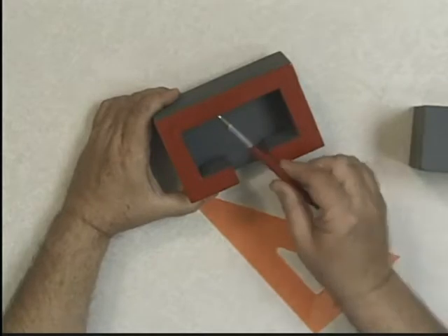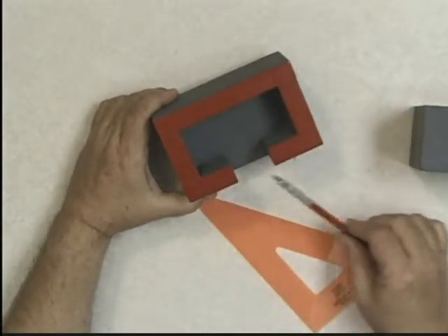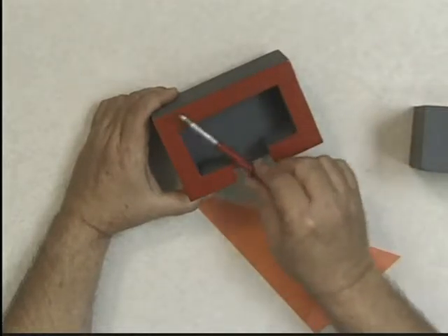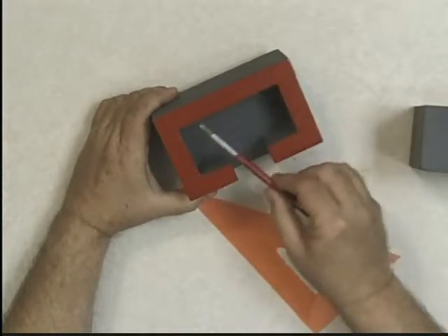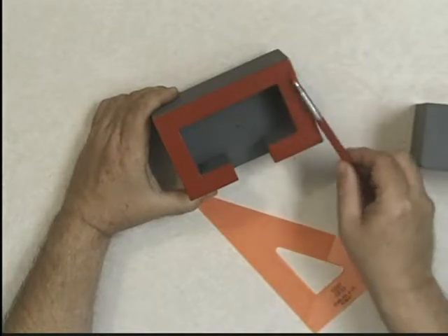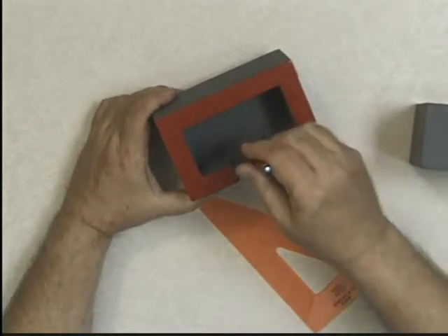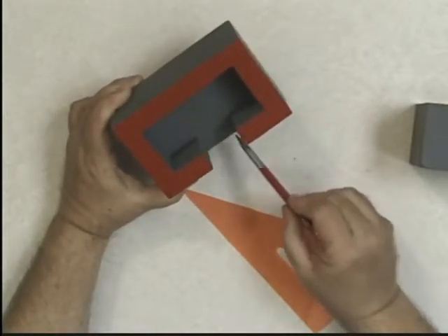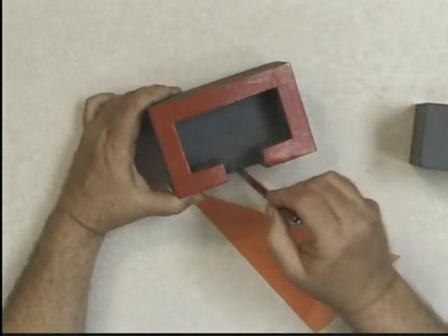But what you have to realize is that we pass an imaginary cutting plane through the object. Part of the object is cut or touched by the cutting plane, and that part that's contacted by the cutting plane, we shade or color it with crosshatch lines. Once we open the object up, we can see things beyond the cutting plane. For example, even though there's a hole in this box, there's not a hole back here, and we would show that bottom or that back interior surface.